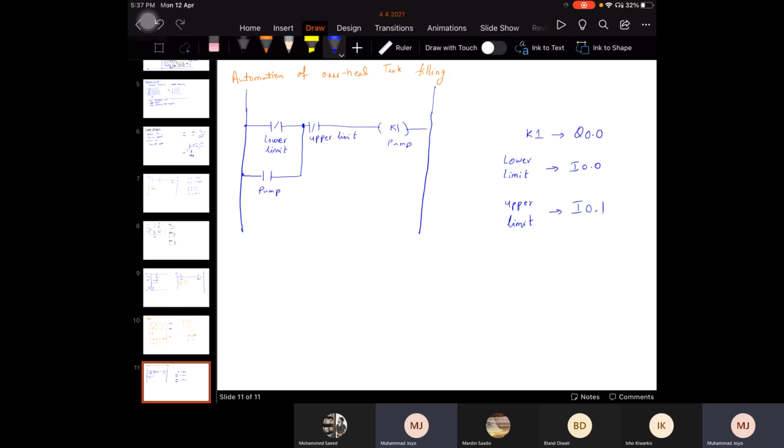There is one thing called MCR. We call it Master Control Relay. Okay. This master control relay acts like a starting switch and a stopping switch. This is basically a relay. We develop a small circuit over here, which is basically a latching circuit.